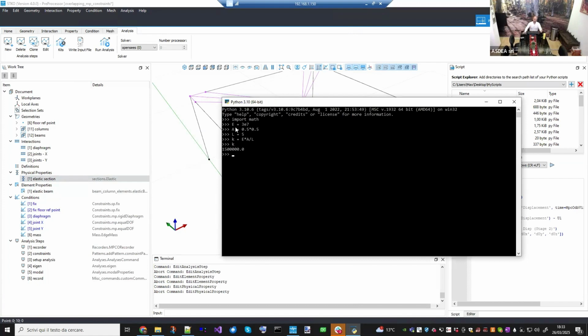Now, for doing this calculation, don't care about an exact value. I just want to know the order of magnitude of the stiffness in my model, because keep in mind that in a very complex model, you don't have only one material and only one area. Also, the finite elements may have different sizes. So just pick the stiffest of them and compute your typical stiffness. Once you have your typical stiffness, you may want to compute the order of magnitude, okay?